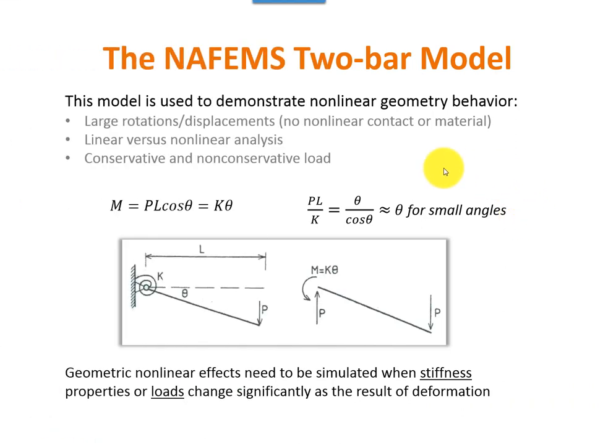This is the NAFEM's model, and it will demonstrate large rotations and displacements. I will have no contacts or plasticity in this model. I will demonstrate linear versus nonlinear analysis, and I will also demonstrate conservative and non-conservative loads. Non-conservative loads are also called follower loads.